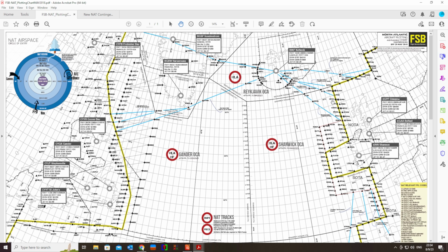There is a case though, those two routes here that I'm showing you in the map, you need to have some sort of clearance to get through that, because this is a North Atlantic oceanic clearance and you need a clearance to cross it. There is no VHF communication within those routes, so you need to have an HF on board.